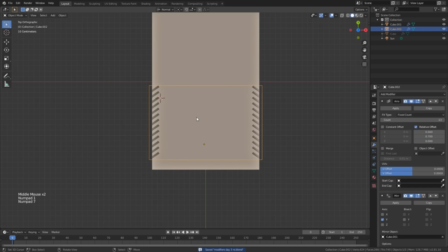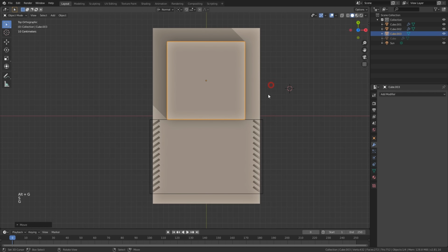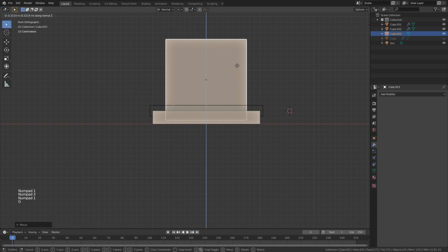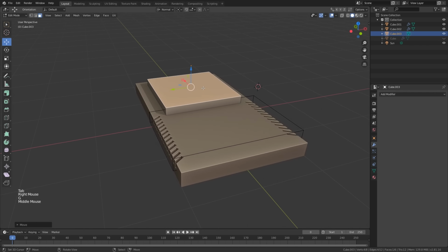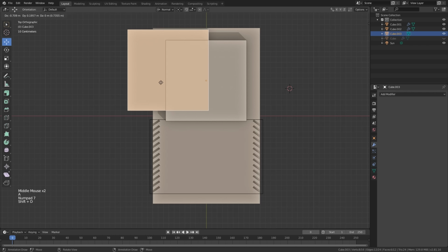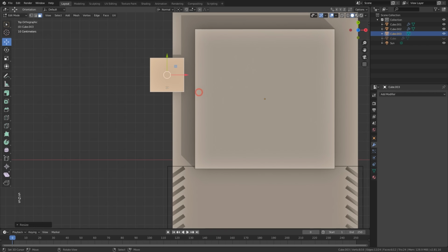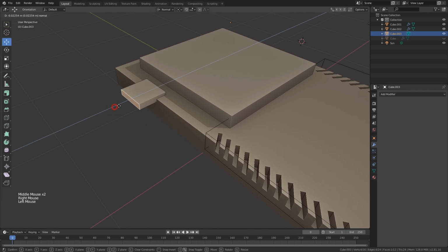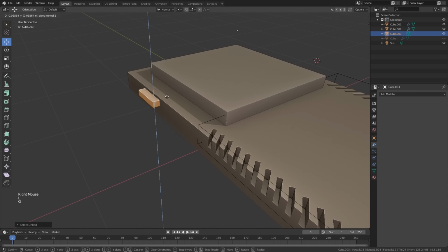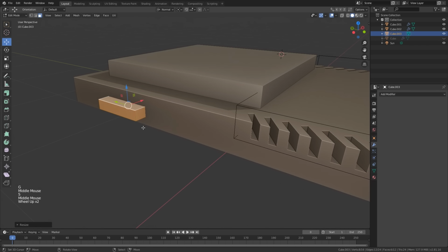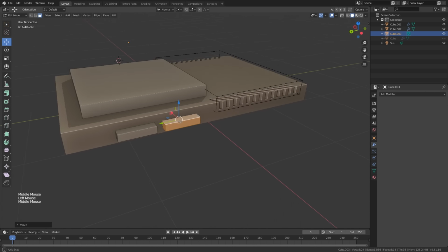you can clearly understand what the benefit of working with modifiers is. Now let's go to top view and bring a cube over here and place it right here, and I can maybe make it not so tall, and I can create a duplicate of this in edit mode. Now I'm creating the duplicate in edit mode so that I don't have to apply too many Boolean modifiers, and I can work with only one, and these two are one object for now. Okay, I'll place it over here, and I can make a duplicate of this again and make another button over here.